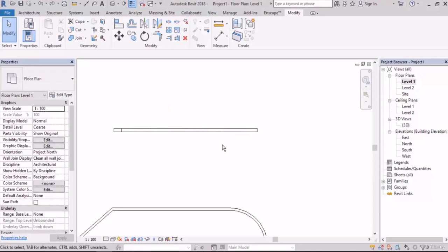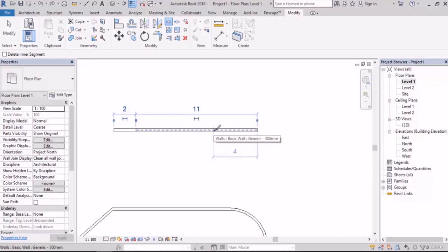Now, how can we give it a size? For example, you want to cut your wall from 2 meters. Well, you can't enter a number at first, but draw your cut and then after you did it, you can enter a number and change it. For example, you want to split your wall from 3 meters that way. So you can't enter the number at first, but drag it as much as you want. And after you did it, you can change the number. It's written on it. And you go on like this.